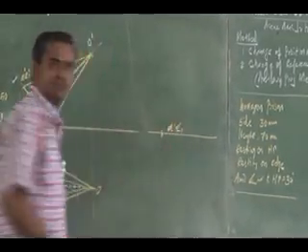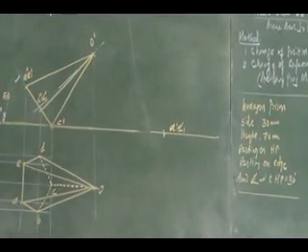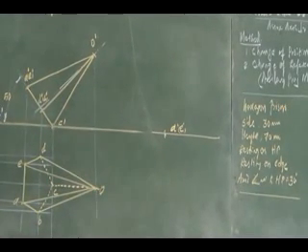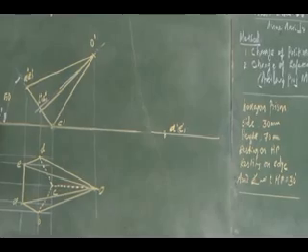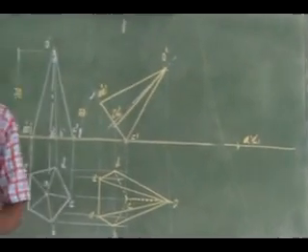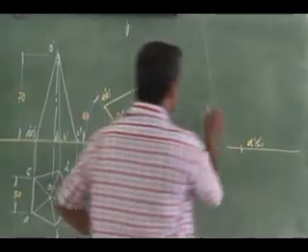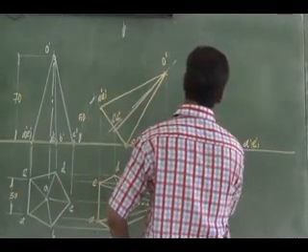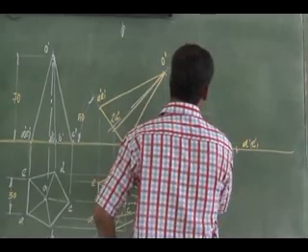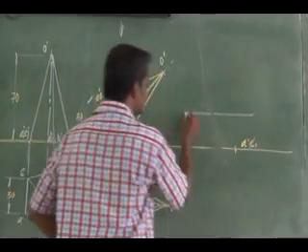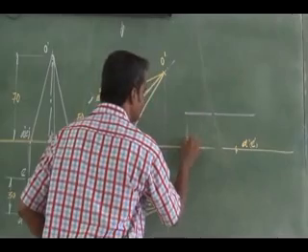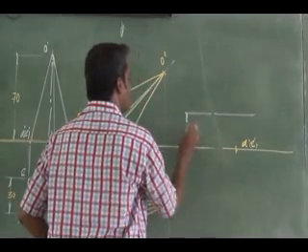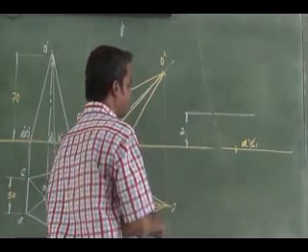A dash, B dash. Then the other opposite corner is C. That C is 25 mm above the ground. So I can draw a 25 mm locus line from the reference line. This is nothing but the height above the ground of that extreme corner. This is 25.